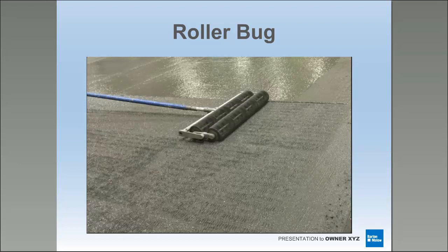But again, if I'm doing an aggregate exposure, this is going to make it really hard to get there, and it's going to take a little more time. So if you're on a job with your placement contractor and he's telling you how he's going to use an edge tamp and a roller bug on everything he does, and it's calling for an aggregate exposure, you're going to want to talk to him. You're going to want him to change his process to help you both succeed at this project.